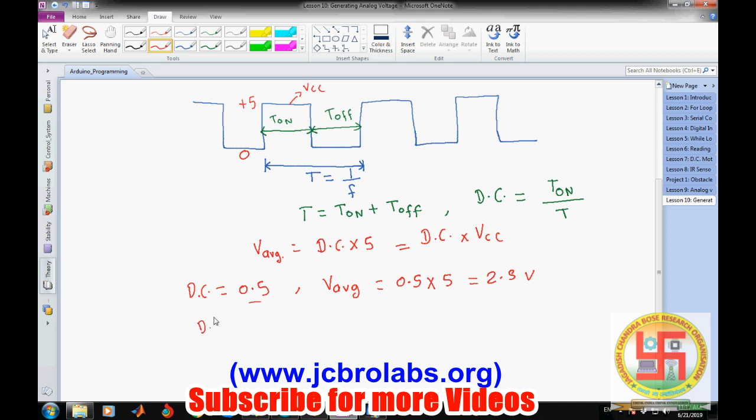Now if we change the duty cycle to 10%, that means 0.1, the V average value will be simply 0.1 into 5, that means 0.5 volt. So just by changing this duty cycle we are changing the average value which is available at a particular pin.